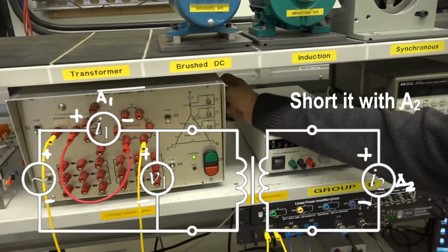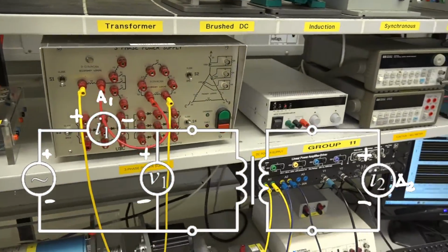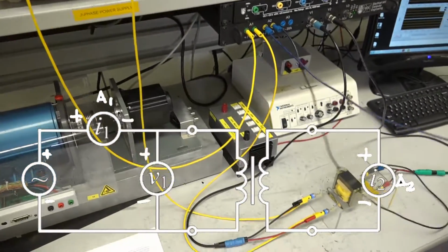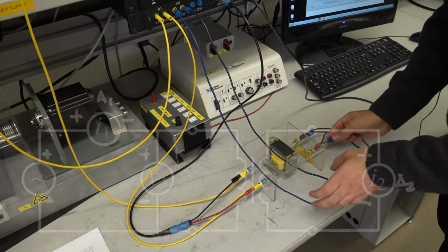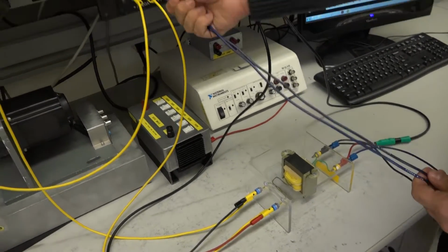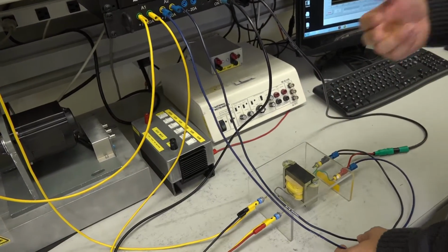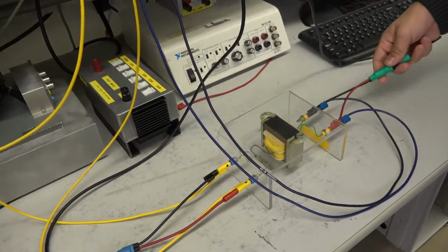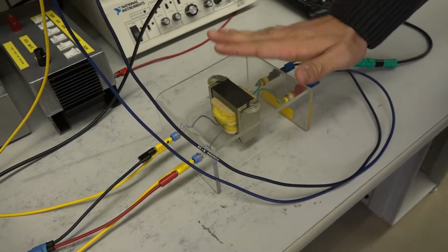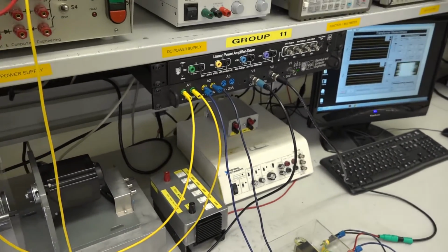We turn the primary voltage back to 0, turn the power supply off, and then we will use 2 wires to short circuit the secondary side through a current meter because we want to read the current that is going through the secondary side when it's shorted. And we can leave the voltmeter connected on the secondary side, but it's going to show 0 voltage because it's short circuited.